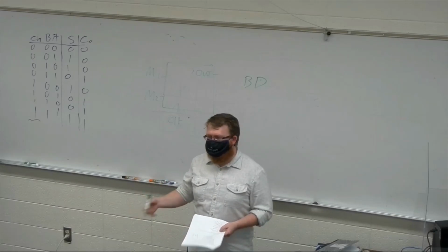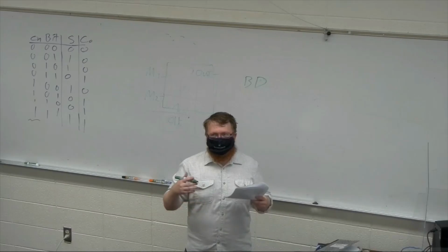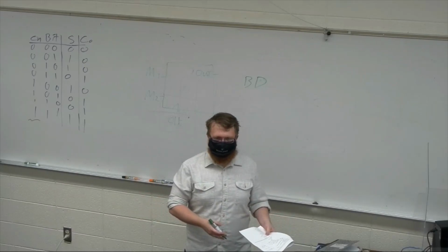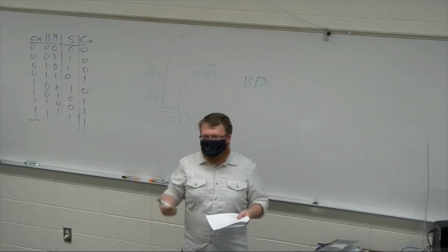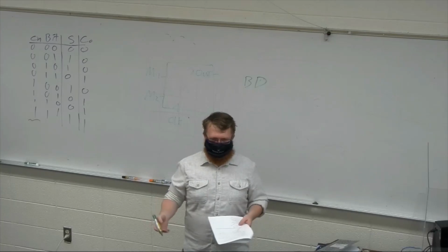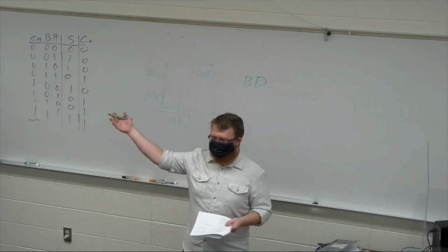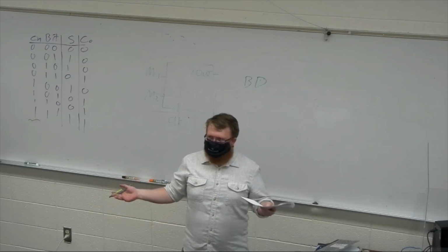The second step is to set the circuit up in such a way that Z changing will affect the outputs. That means X has to be 1 and Y has to be 1 because they're inputs to the AND gate. If Z goes into an AND gate and the other input is 0, the output of that AND gate is going to do nothing.